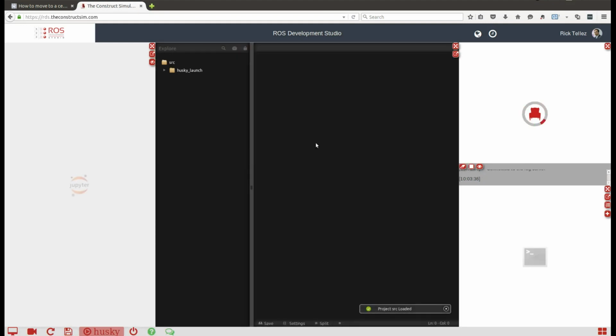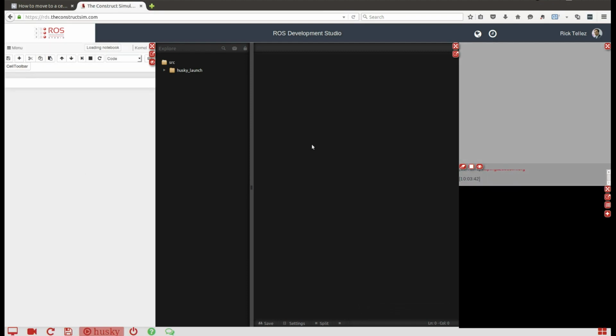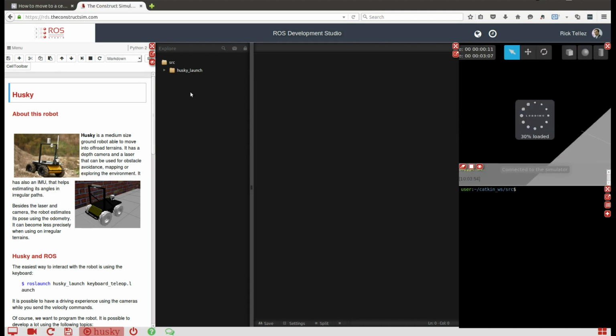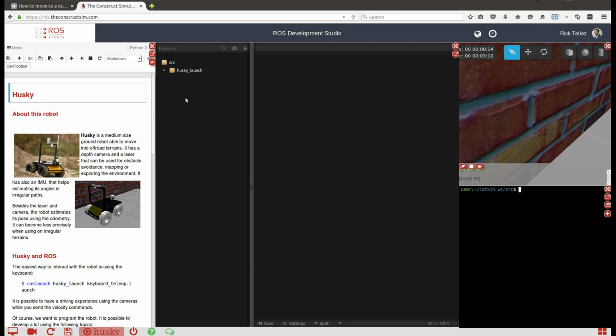Great. So take into account that in this exercise, we are not going to talk about obstacle avoidance or localization. We are going to assume that the localization of the robot is actually the odometry value. In case you want to dedicate yourself to work with navigation, you must know that odometry contains a lot of error that accumulates over time. So it's not a very good resource to plan navigation of a robot, but it can be used quite well for other topics.